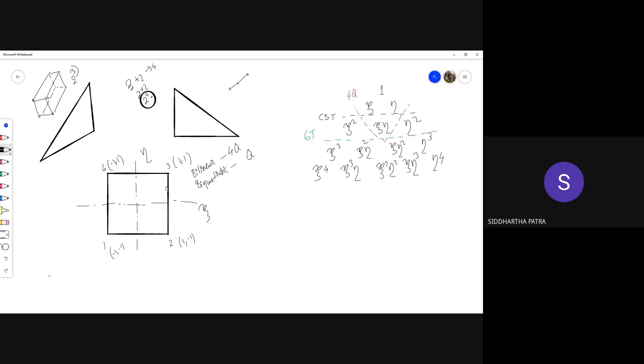for a quadratic 2D element? 3 squared. And how much is that? 9, right? So it's a 9 noded quad element. Okay. And in Pascal's triangle, this is how it looks like. These are the terms that would contribute to the 9 noded quad element.